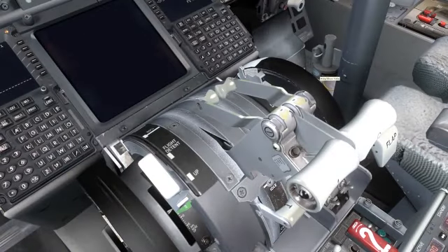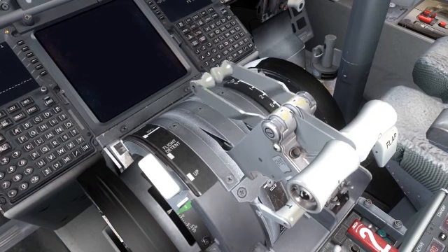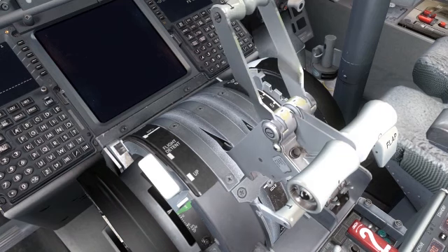Thrust reversers are operated with the thrust reverser lever, located immediately forward of the engine normal thrust levers. The reverse thrust levers have to be lifted aft to deploy reverse thrust. The reverse thrust levers have 3 detents. Detent 1, idle reverse thrust. Detent 2, normal operating reverse thrust. Detent 3, maximum reverse thrust.